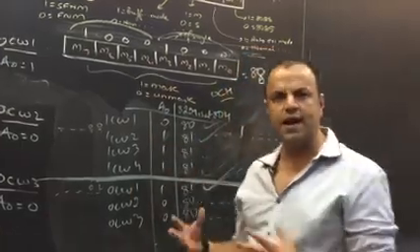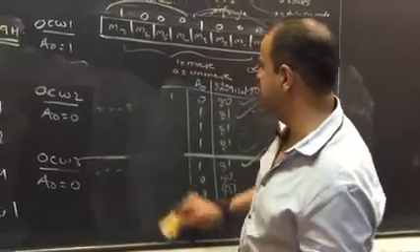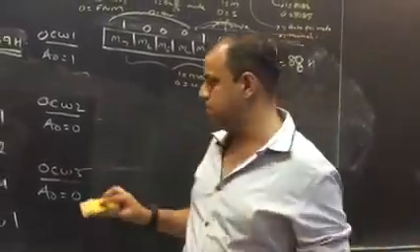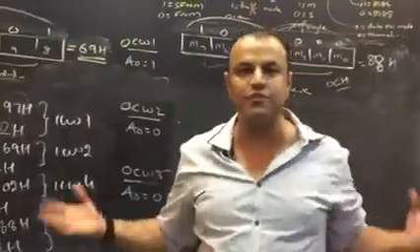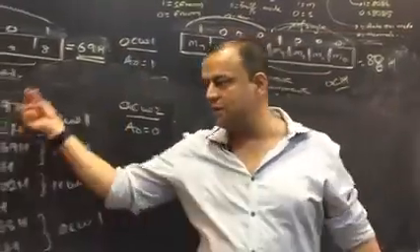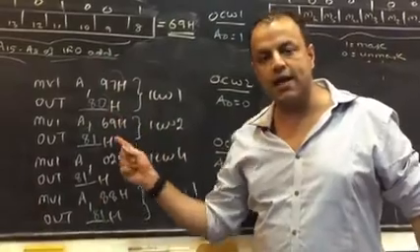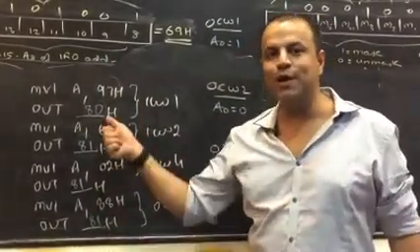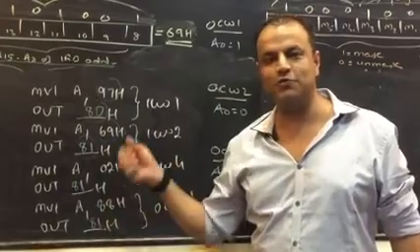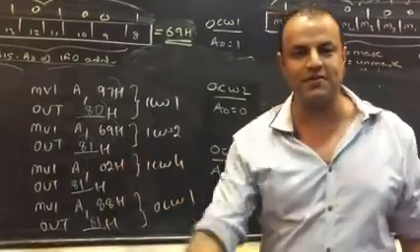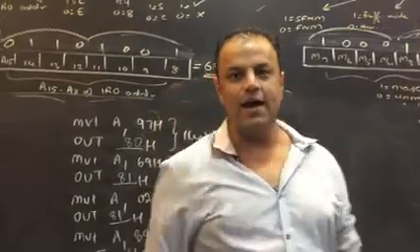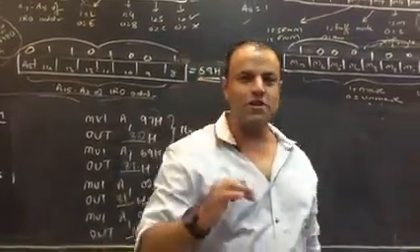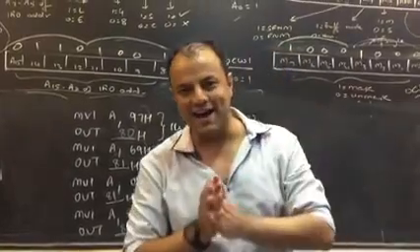Tell me, did you understand how 8259 identifies all the 7 commands? Now, like I said, you're not going to explain this to anybody. This is not the part that gives you marks. What gives you marks is drawing the commands, getting the command values right, giving the program correctly at the correct addresses. But if you haven't understood that, you'll have to mug up the addresses. If you understood it, you know which command is given at which address. ICW1 is given at 80, ICW2, 3, 4 are given at 81, OCW1 is given at 81, OCW2 and 3 are given at 80. Please tell me, are you clear?